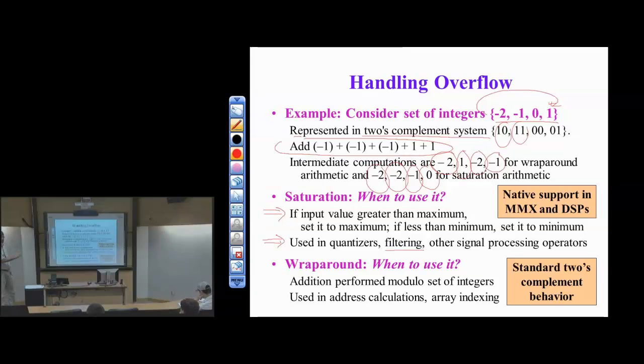We tend to prefer saturating arithmetic when it's available because what we really care about is how strongly I am responding to an input. Is it strong or weak? If it's really strong, then we'll saturate to some value. And if it's really weak, then it'll be something close to 0. So in signal processing, we tend to go with saturation arithmetic. Or if we do the wraparound, then we have to scale all the calculations so we don't go outside of the range of values, which reduces our resolution in the amplitude domain. So there are some downsides to that.